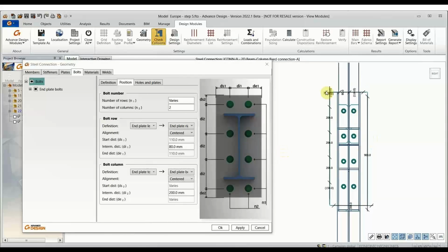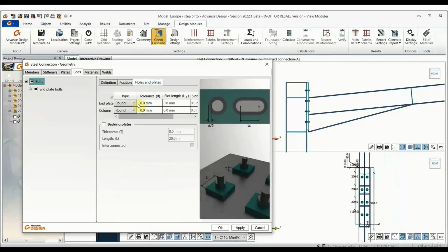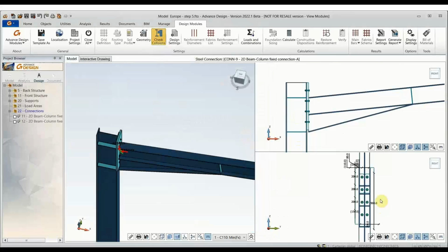And I think those bolts are too close to the flange there. I'm expecting that to be probably too close to the welds there, so we'll see that as an error pop up. Your holes, you get control over what that hole looks like. So your round, countersunk, or slotted holes, if you have a deflection head, you're going to be allowed the beam to move in some cases.